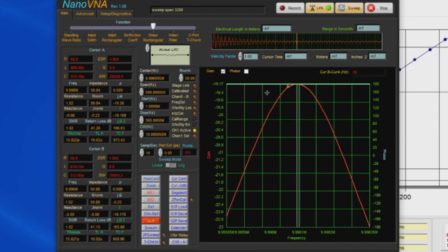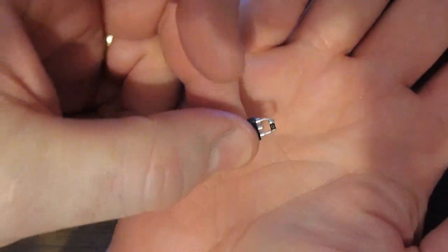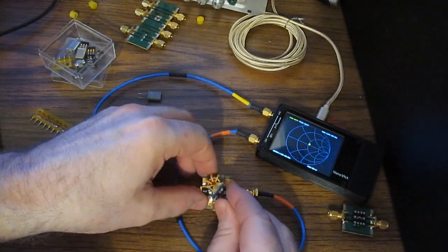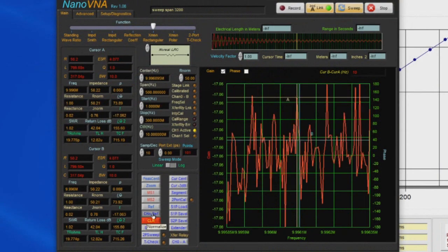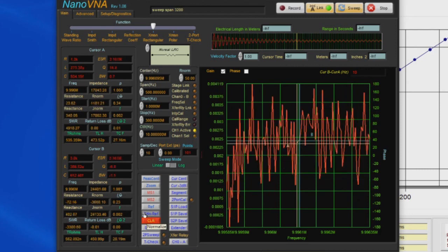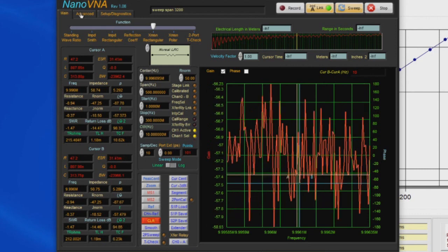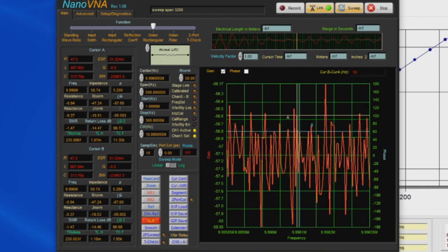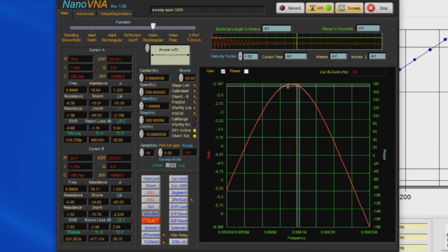So this unit has to be calibrated, and again, the way we're going to do that is to apply a short in place of the crystal. We'll store that as our reference point, and let's go ahead and select our channel N-ref. And again, we can see we're at 0 dB, and let's go ahead and insert our crystal now, and it should be, yeah, minus 2 dB down or so, and that would be normal for this particular crystal.